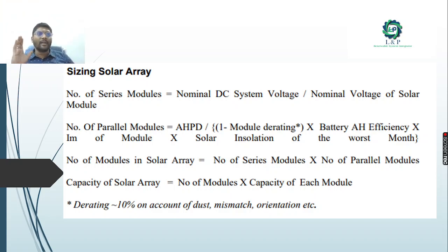Always make a design where, normally, the minimum efficiency of your panels might be around 19% or 20% or 21.4%. So in such cases, please make conscious decisions in your planning. For example, when you're planning for a 1 kVA system, then for your solar panels you need to plan a minimum of 1.2 or 1.4 or 1.5. If it is more than that, then it is good, because you can't expect 100% output in solar.